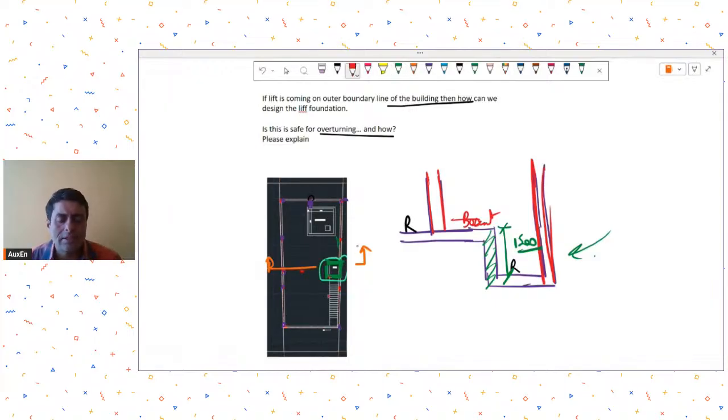If there were heavy lateral loads, and on this column there were large moments for which you are worried, then if your soil allows, maybe you can think of providing piles over here to take that additional uplift or tension force that might get generated. Because you are not able to extend the footing beyond this face.